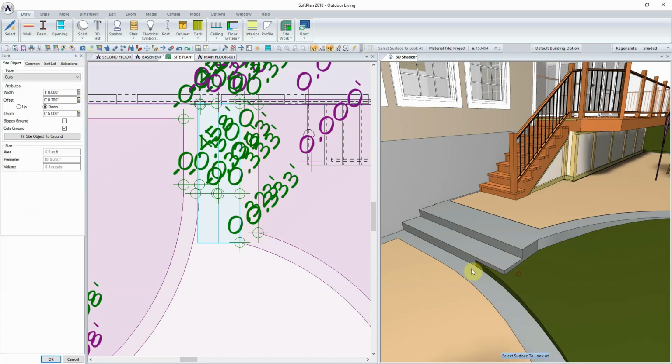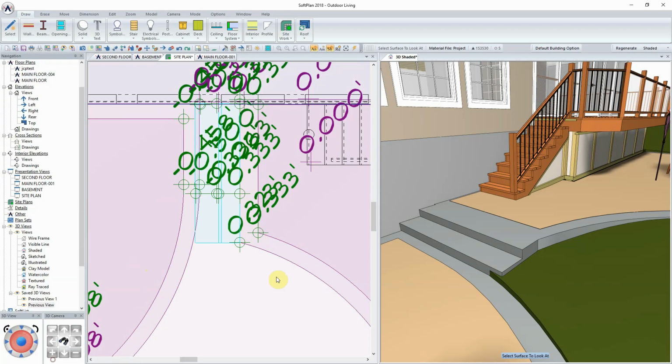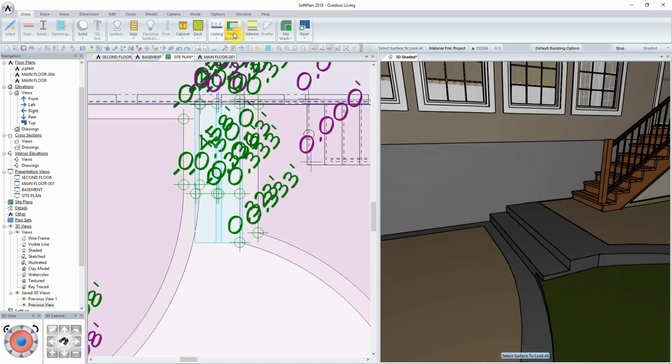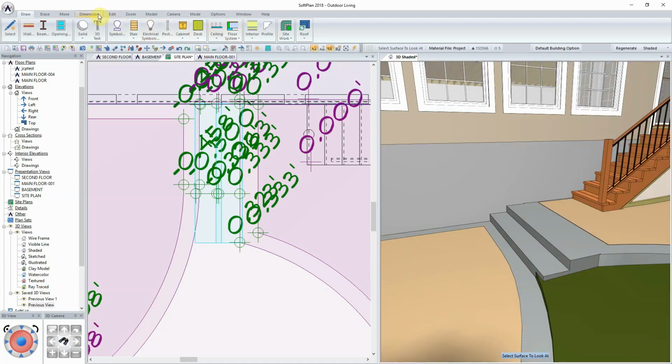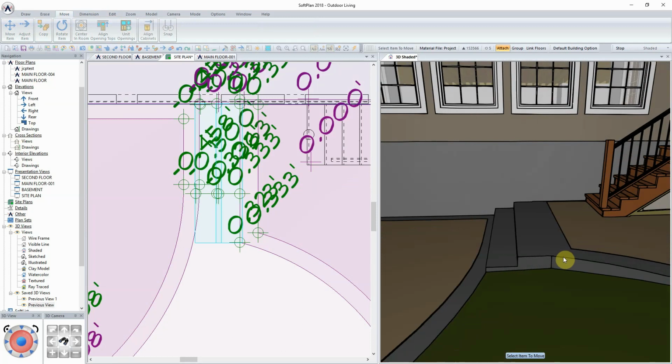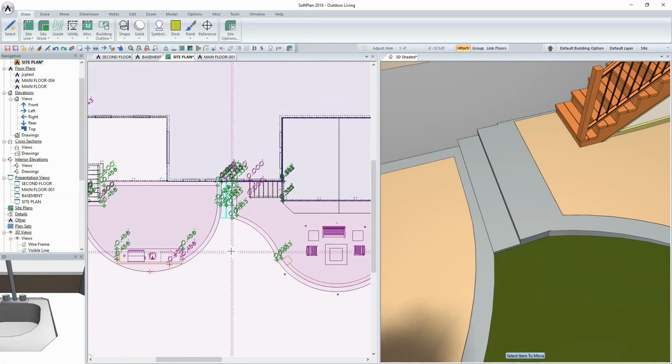And so in this case here, I'm going to edit this staircase, which currently right now has a width of say 12 inches, which is what we can see. And as I edit this, I could maybe make this a little bit deeper, or wider, if you will, and do the same thing with this one. And as I do that, just to make this a more gentle staircase going up with much wider treads, I can also have the ability now to move this staircase forward just a little bit because I've got that much more depth as far as their dimensions are concerned. Once I have done this and I've got my stairs in place per se with the 15-inch,